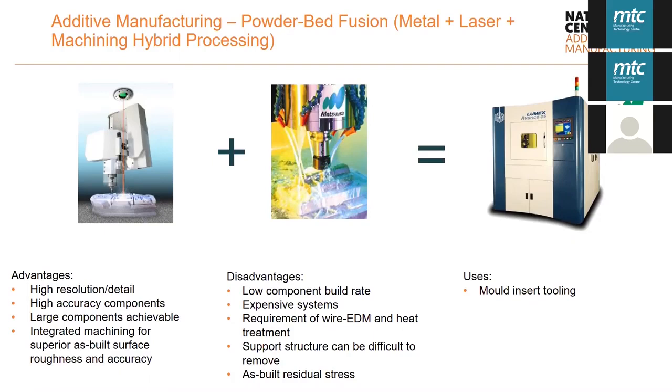It will allow you to have a much better as-built surface finish and as-built accuracy than your conventional LPBF component. But these systems can be quite expensive, and again, you do need to heat treat and wire EDM in some cases, and some support structures are still present because of the overhangs that you're manufacturing.